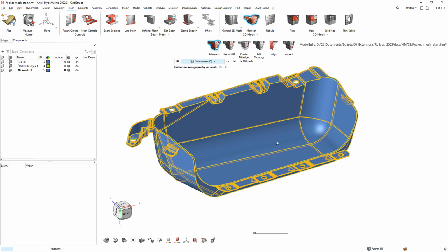And what this is doing in the background, underlying the direct mid-mesh tool, is FE geometry. So this is the concept of combining topology with mesh and allows CAD and mesh to exist in a single entity. This has a couple of massive time savings. So firstly, the tools that I've used so far, things like stitch and split, are all accessible for both CAD and for the FE.